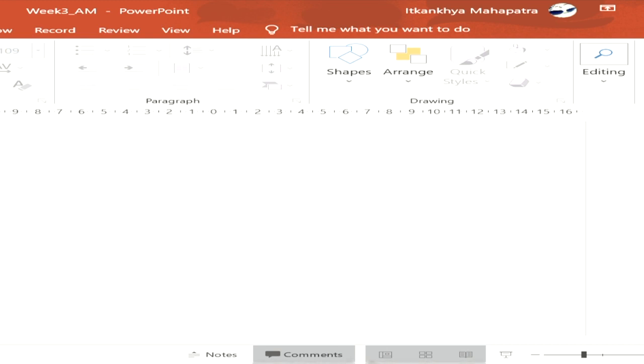Now this is about the raster path. Next is the zigzag tool path. The zigzag tool path is also known as direction parallel tool path. This is the most commonly used tool path in additive manufacturing because it has less build time and fewer transition motions.